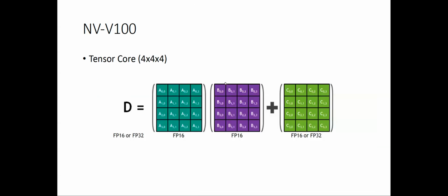All these tensor cores are nothing but matrix multiply units, and they support different shapes of matrix multiply. This is an example of how a tensor core supports a 4x4x4 matrix multiply within one instruction. You can think of it as each clock cycle we can get 64 MAC unit computations within this tensor core. That's a very high intensity unit.